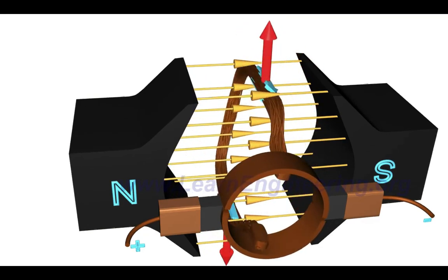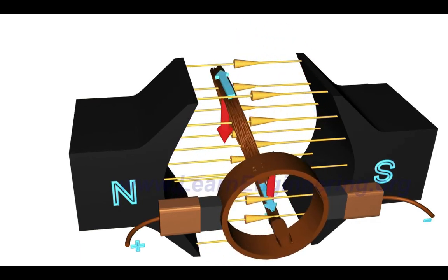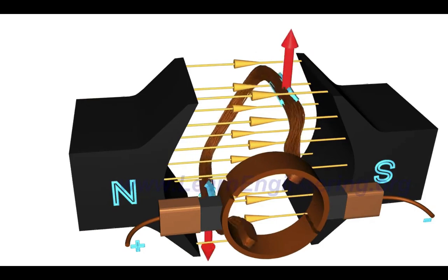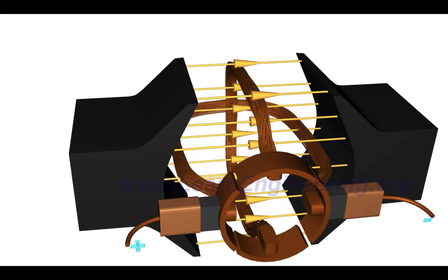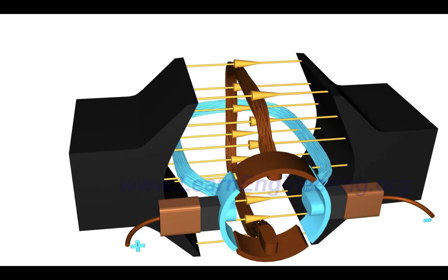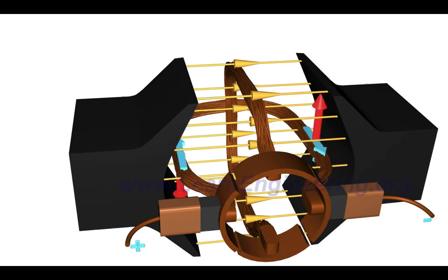It's pretty cool how they can show that in the animation too. This is like, I can't reproduce this. It's going to get more torque and then less, more, and less. Here is the trick to overcoming this problem. Add one more loop to the rotor, with a separate commutator pair for it. In this arrangement, when the first loop is in the vertical position, the second loop will be connected to the power source. So a motive force is always present in the system. Smart.